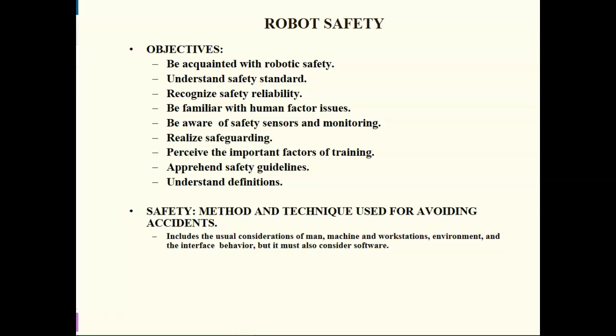So one of the things you need to be doing is be acquainted with robotic safety. So don't get in the cage with them. Watch out for pinch points, things like that. Understand safety standards, because that is going to be both the international safety standards as well as the safety standards of wherever you're working at the time.